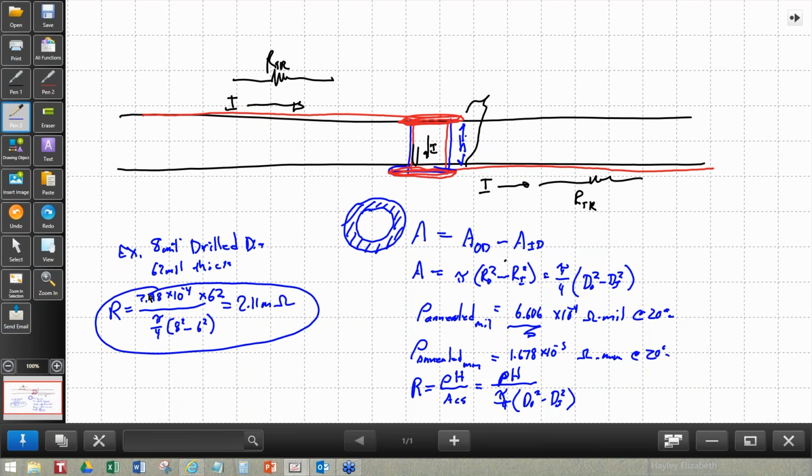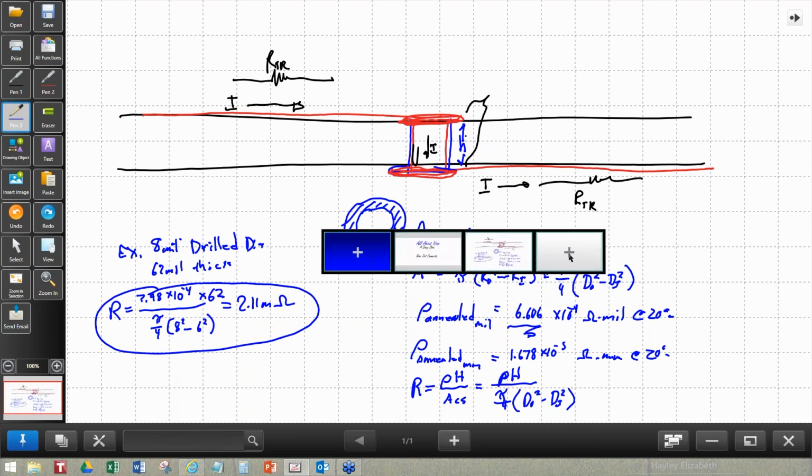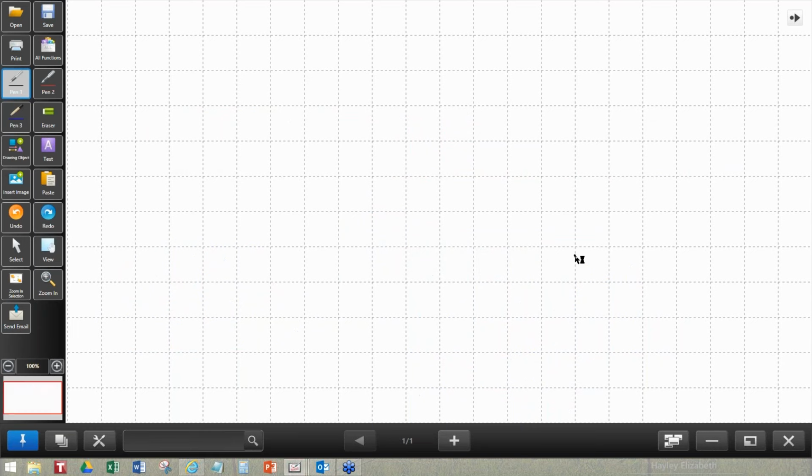Things get a little bit more tricky if you start talking about high speeds, though, because skin effect now has a problem in that as you go up in frequency, if you have a conductive sheet of metal, and now you have an electric field, and the field tries to penetrate through the conductive material, you end up causing currents to flow in the surface which oppose that.